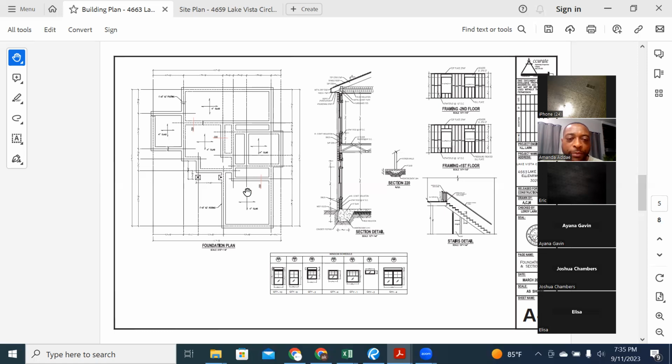So these are your grade beams. Interior is your grade beams. The difference, as I said, with your grade beam, although you have it just as wide as your footing, is just for your support walls, whereas your footing is for all your exterior wall, okay? But the interior grade beam is the same width in our plans as the footing.